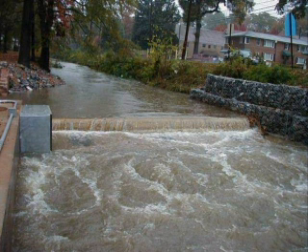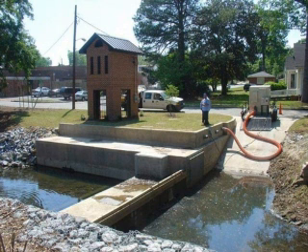As you go down through this filter, you get smaller and smaller voids, and that's where the small particles get removed. When the wet weather occurs, the flow starts to go into the filter system. The first thing it does, it enters the influent structure on the other side of these bladders, and the bladders actually compress that media, causing the top to be uncompressed and the bottom to be compressed. This is a picture before the flow actually goes into the filter.